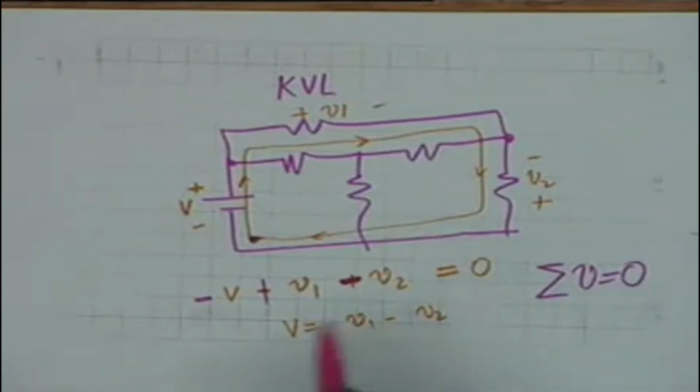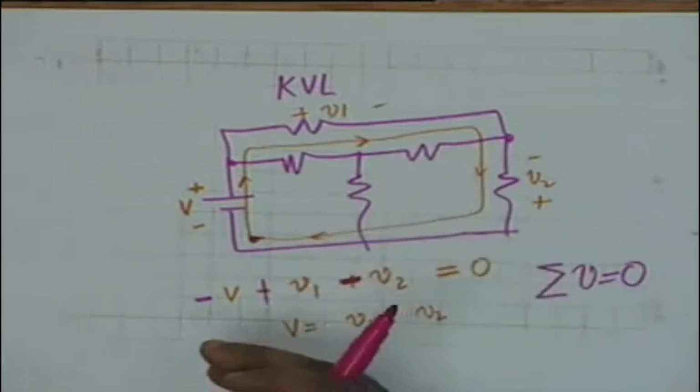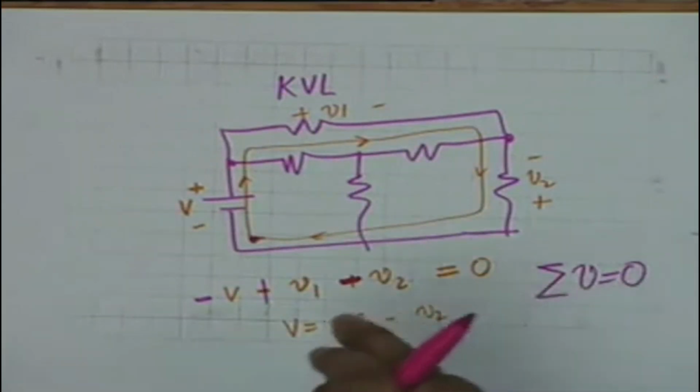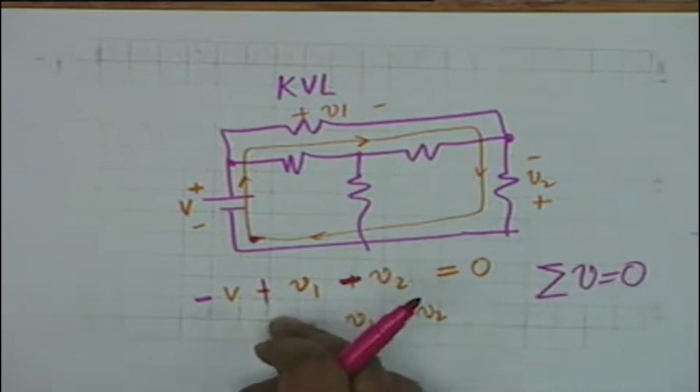And if you take a unit positive charge through a potential difference of V, obviously the work done is V, and if you take it in the direction of potential drop, work done is positive. If you take it in the opposite direction, work done is negative, and that unit positive charge, or any charge Q, cancels out from both sides, and therefore you are left with only voltages or potential differences, and this basically is KVL. Did you know of this interpretation earlier? Yes,